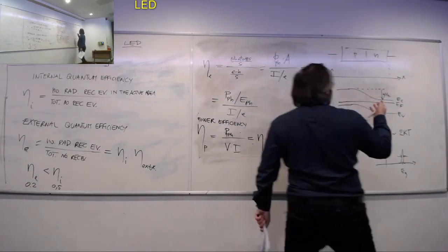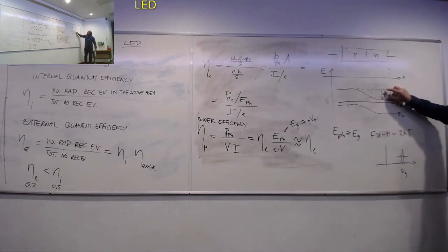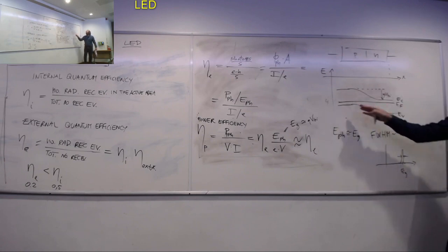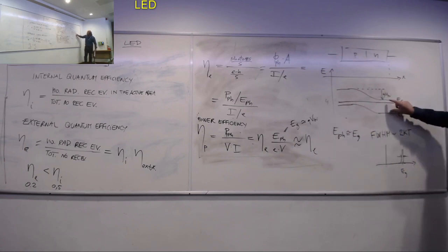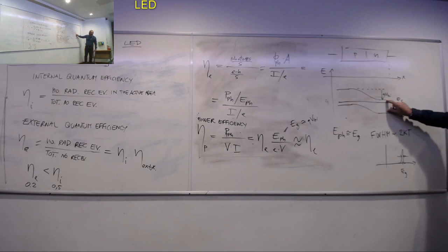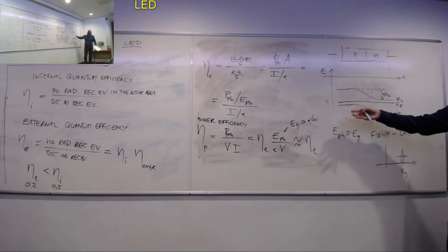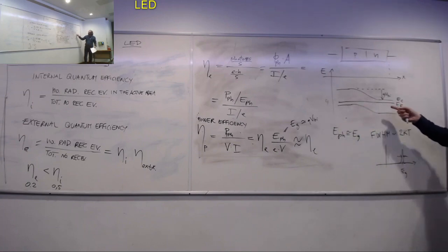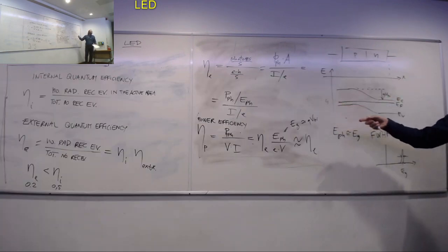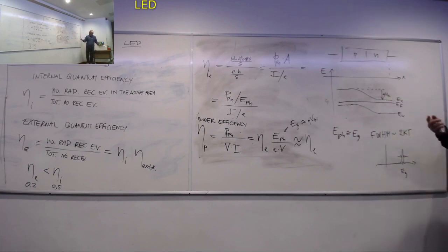So as you can see from here, QVBI is defined as the difference in the conduction band between the P and the N side, or the valence band is the same. But this quantity is very close to the band gap. You can also see it for yourself that VBI is indeed very close to it, and this is because this side is very much P, this is very N. So the Fermi level on one side is very close to the conduction band, on the other side is very close to the valence band, and that's the reason why VBI is very close to the band gap, okay?